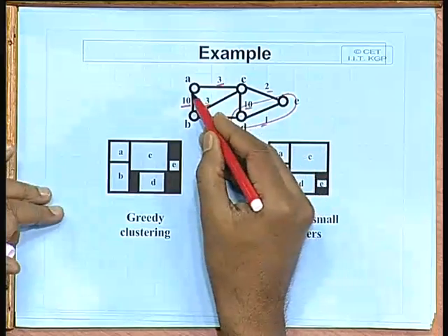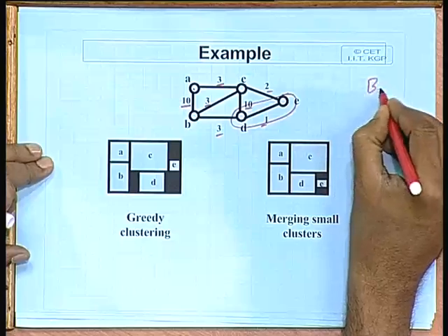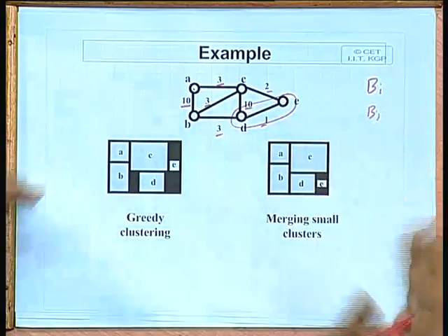So how do we know that E is a small cluster? That information will be given, because when you are doing floor planning, I am saying that you are given the blocks Bi, Bj. So each block will have some width or height, or in terms of gates, the number of gates, some information is given. Because here bottom up is a natural approach, but you can also think of a top down approach for floor planning.